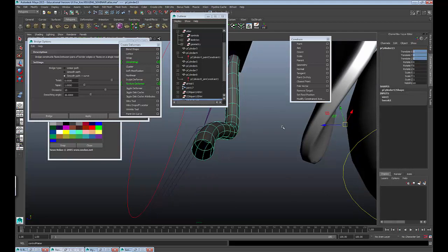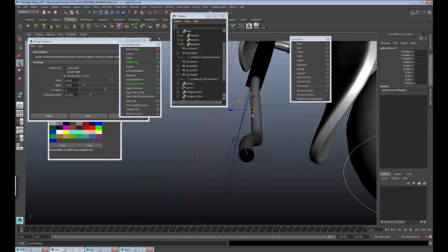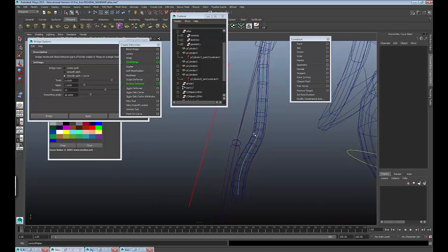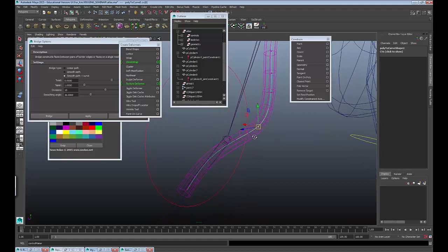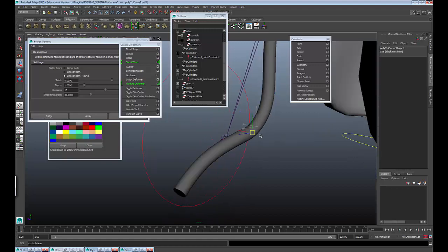So if I go into the actual wire tool, we've got this thing called drop-off distance, which is in units. So you just want to go quite high with that. Let's go 50 at first. So now when I move this around, this should stick and move exactly with that wire. And if I grab any of these verts on the wire, this is going to move around with that as well.